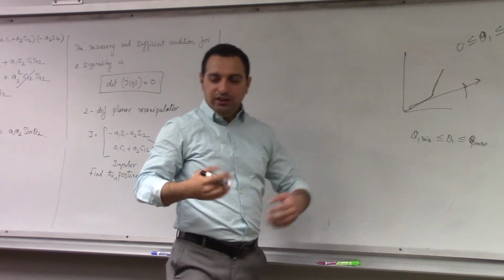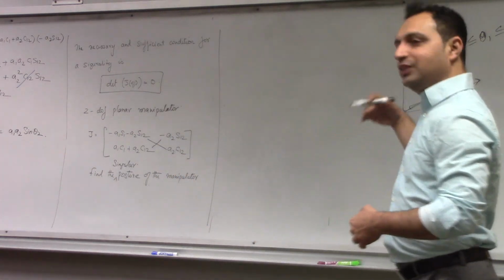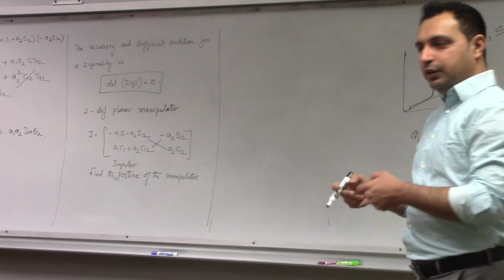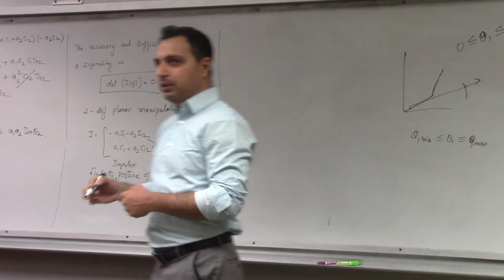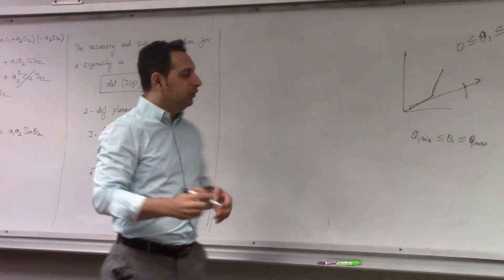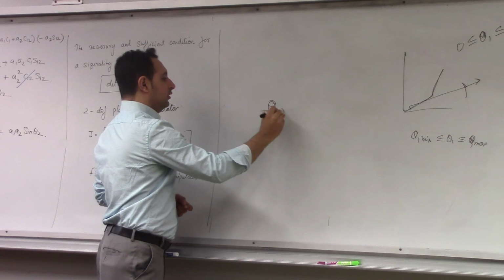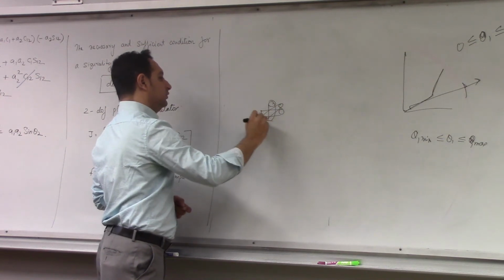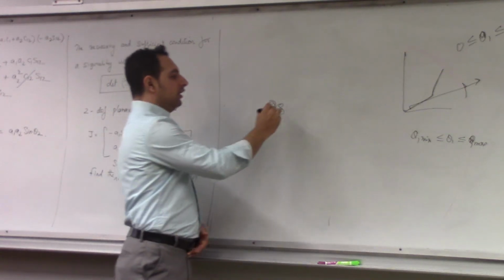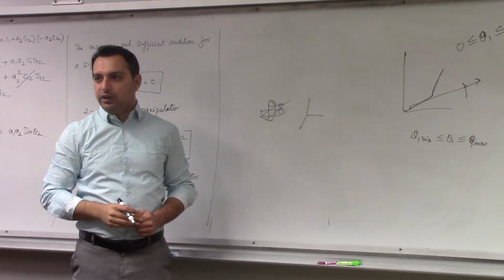So it is visually easy to understand in some geometric configurations, but when you go to 6 or 7 degrees of freedom, somebody who is operating this or designing a path planning application cannot tell if this is a singular posture or not. If you look at the wrist, you have 3 joints here. Technically, this will give me motion along 3 different axes.